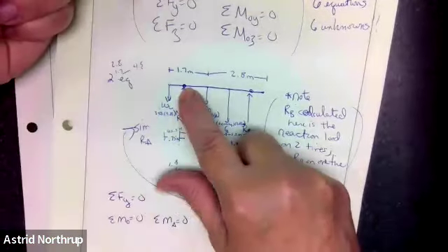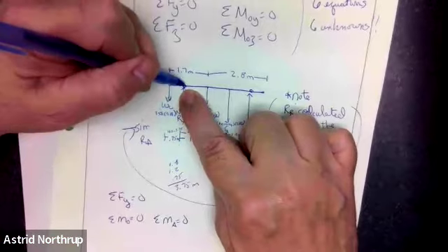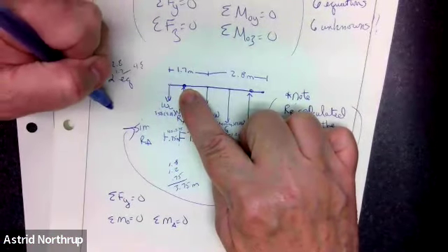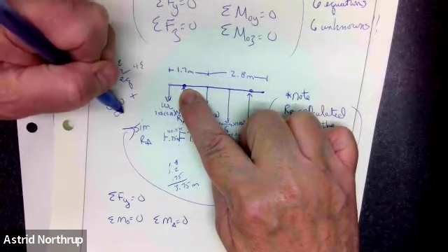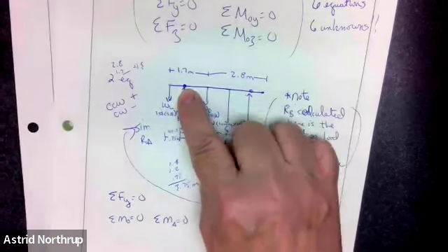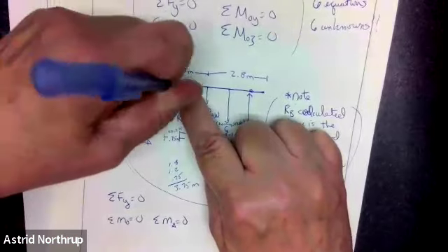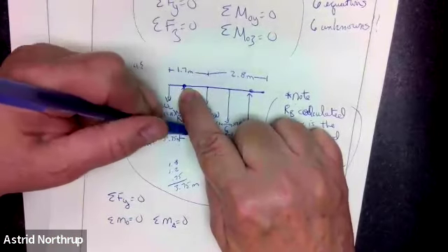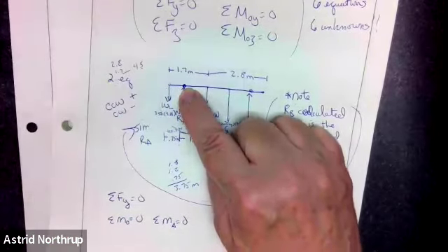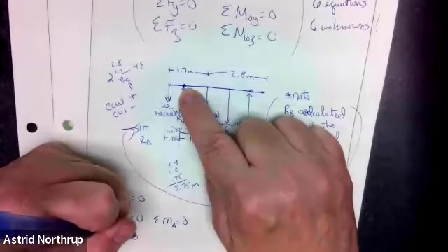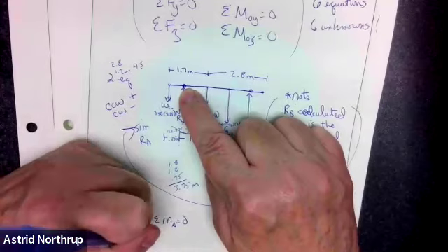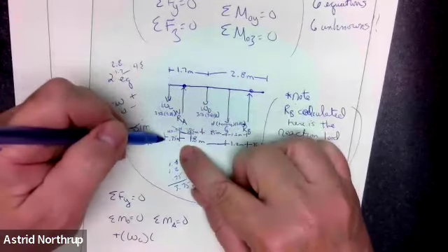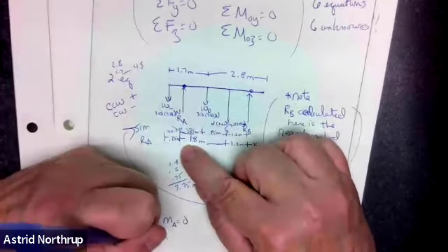The way that you can compute this is, remember from the right-hand rule, a counterclockwise moment is positive and a clockwise moment is negative. So if you think about putting a pin here, this is my pivot point. W sub C will make a counterclockwise moment, so that's going to be positive. This distance is going to be 0.75.